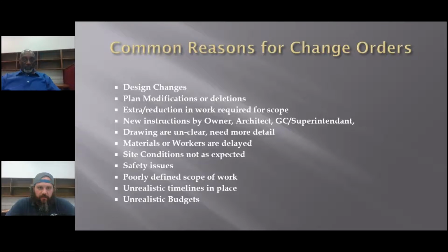If drawings on the architectural side are unclear or need to be more detailed, if the materials or workers are delayed like we talked about, site conditions are not as expected. For us putting up buildings, I'm sure road construction is similar. When you get out to a site, sometimes you're dealing with the rainy springtime season that we've had for the past few weeks here, and everything's muddy. They don't have good stone brought in to bring up the compaction, and it's just a lot more difficult to work in that area. That could be a potential discussion for a change order.